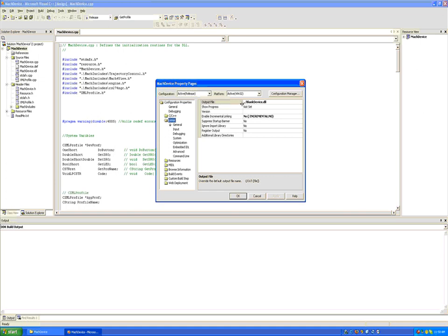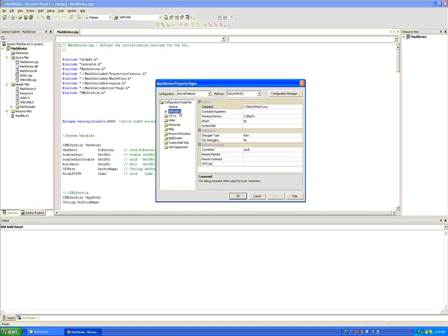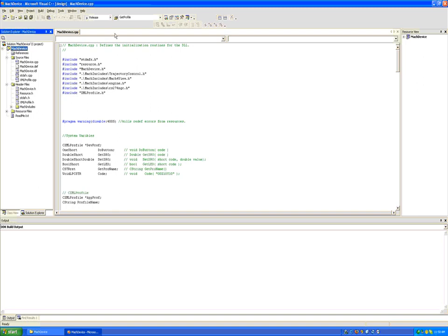You'll notice that I've changed it to /blankdevice so that the DLL will be placed into the plugins folder. It goes back one folder, in other words, and places itself in plugins. Also, for debugging purposes, under the debugging tab, you'll see under command I have set it to C Mach3 Mach3.exe with a working directory of C Mach3. This allows me to run the add-in or plug-in that I'm doing and do proper debugging. I'm going to switch this to debug so I can show you an example.